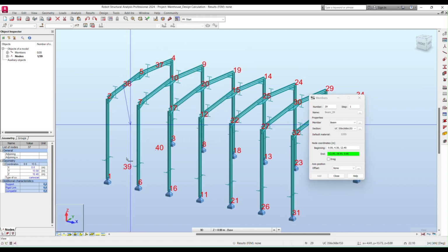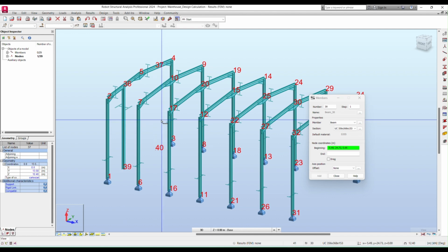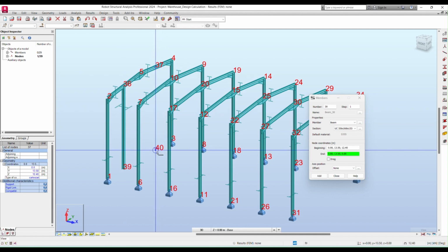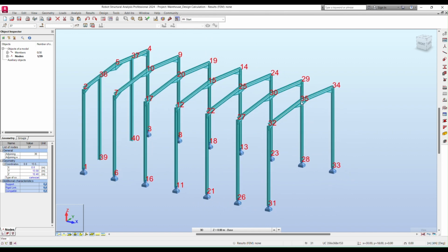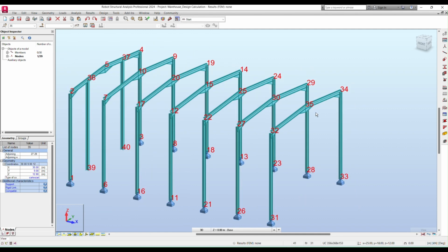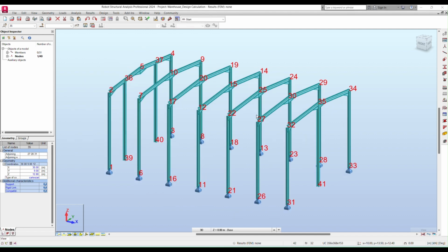So this we need to connect this way. So the wind post is in the correct position, in this direction, and one more wind post we need to add here at the end of the width in the portal, the same way. So now the wind post is added, and similarly we need to add the support condition also. So for the reactions,